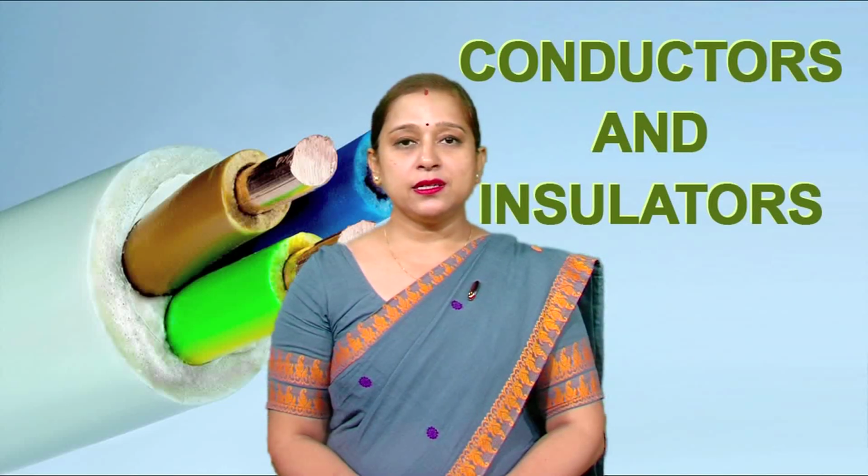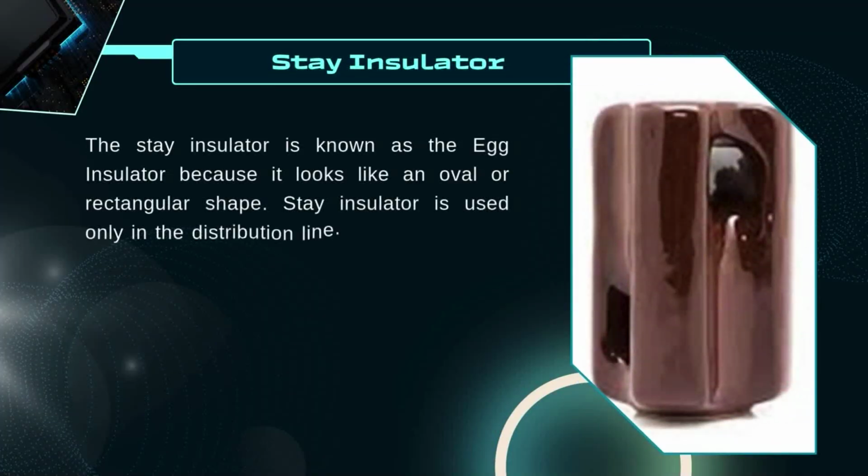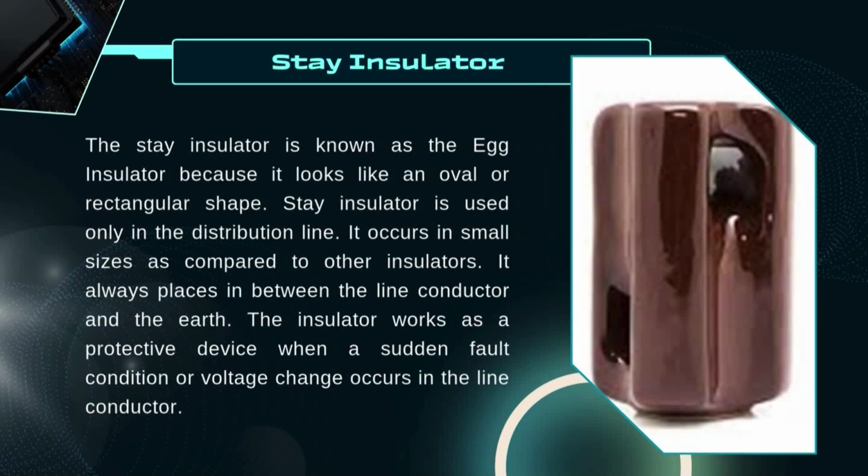The last insulator is the stay insulator. This stay insulator is known as the egg insulator because it looks like an oval or rectangular shape. Stay insulator is used only in the distribution line. It occurs in small sizes as compared to other insulators. It is always placed in between the line conductor and the earth. The insulator works as a protective device when a sudden fault condition or voltage change occurs in the line conductor.